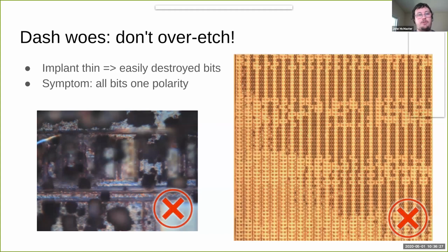At that point, all of the implant was etched through, and it just starts destroying the data. If you let it sit for a very long time, you'll get something like the image to the left, where this chip has been very much pitted and all of the data has been destroyed. The chip itself is completely destroyed, just not very usable. So you need to very carefully time these reactions.